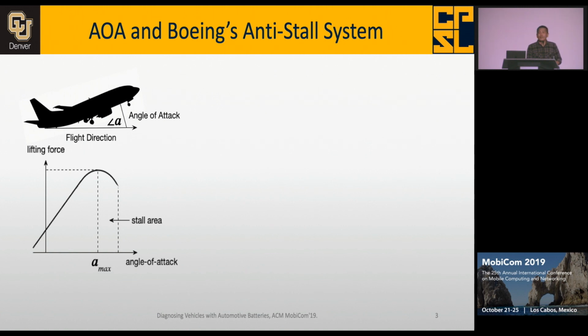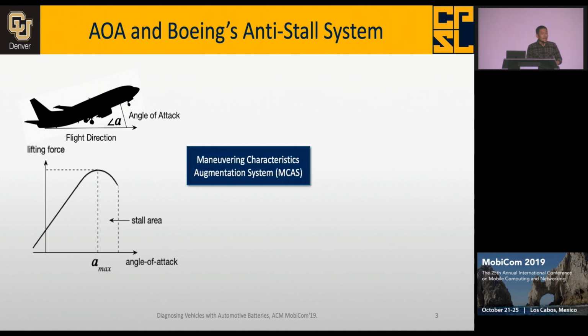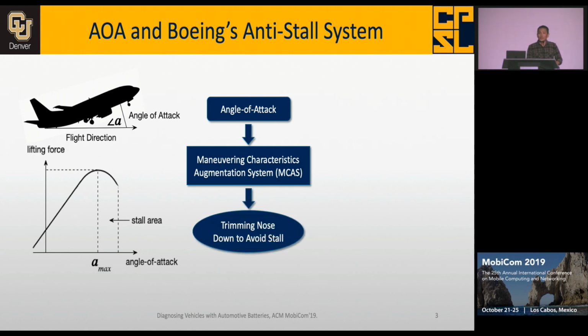And on this Boeing 737, they have a control system or control module called MCAS. This control module takes input from this AOA sensor to see if the alpha is too large or not. And if it's too large, it will take the nose of the aircraft going down. It does this by imposing two forces, one to the head of the aircraft and the other to the end, one in the up direction and the other in the down direction. So this is the normal case.